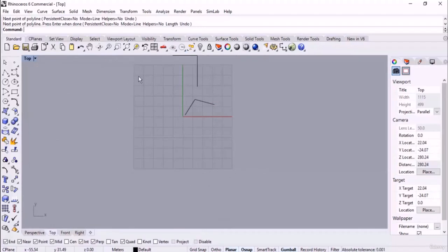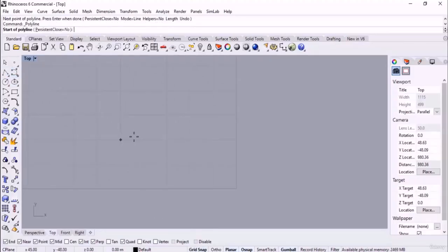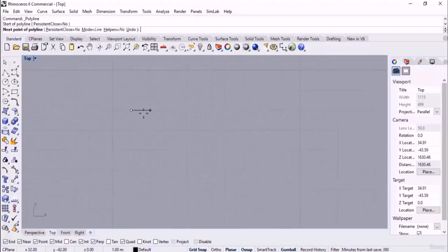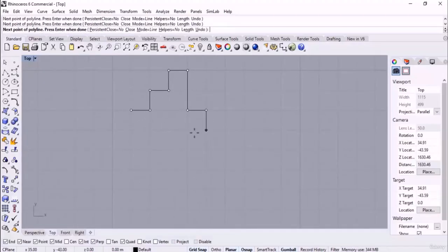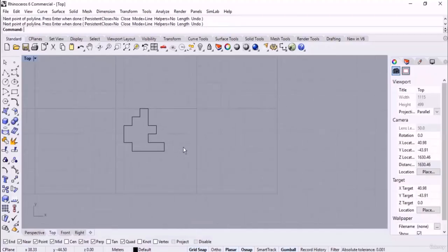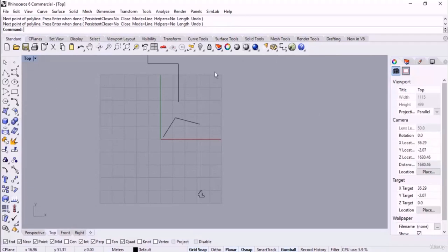However, here we got grid snap as well. As you can see, I explained the grid lines in the last sessions, which is an array of lines lying on a portion of the construction plane in the viewport. Here, if I activate the grid snap, as you can see, grid snap constrains the marker to the crossing points of the grid, which is used for modular designing. And as the unit is specified to 1 meter, check this out, it constrains the marker to the crossing points of the grid. Then we can have modular designing.